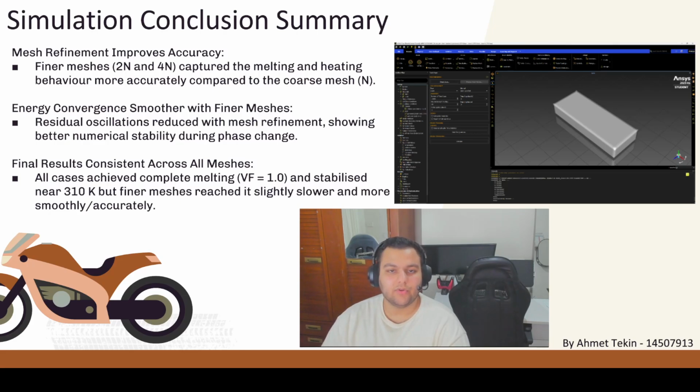The volume fraction achieved one at around 2 hours and stabilized at 310 Kelvin, which was what we set at 10,800 steps. Finer meshes reach it slightly slower, and more smoothly and accurately, as expected from real life.